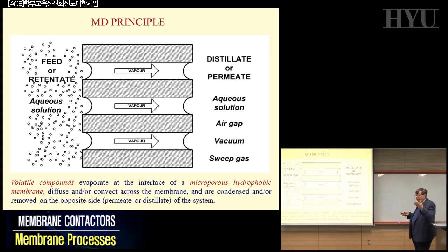If you go to 80 degrees here, you can compete with reverse osmosis in terms of flux. Otherwise, if you are working at room temperature, which is what we are trying to do today, to operate at very low temperature so you don't use too much energy, or you can use solar energy, which is impossible in traditional evaporation, you have less transmembrane flux than competitive technology, just because not too many molecules can go into the vapor phase.